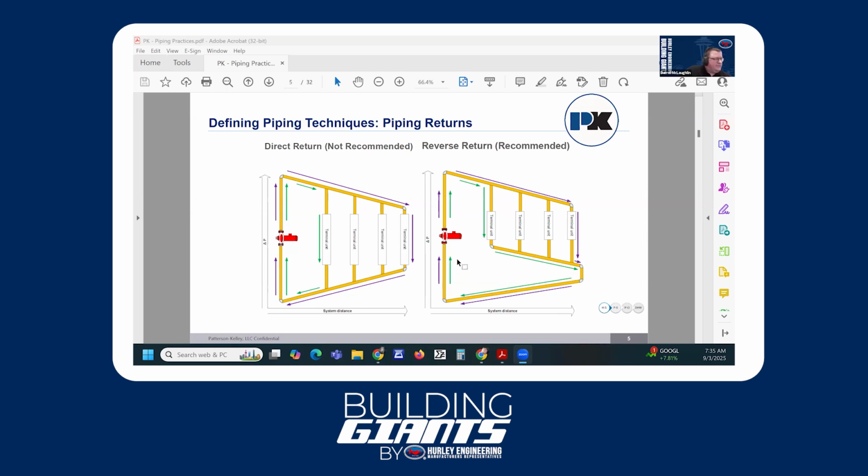In the system to the right here, this is a reverse return. So what we're trying to accomplish here is the first unit that we arrive at on our flow will be the last one out on our return. So here we're the first one in, the fourth one out. The second one would be the second one in, and the third one out. Then the third one in, second out, fourth in, first out. And by doing a reverse return like that, it's self-balancing.